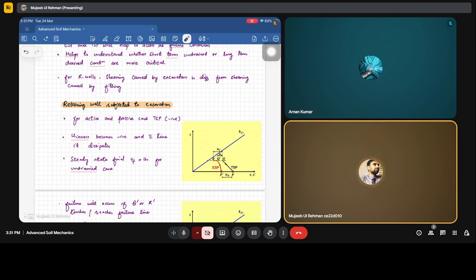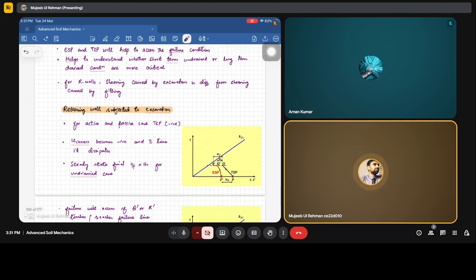We reach point Q. Now when we are doing the excavation, we are taking the soil out. You have to remember that in case of sampling, when we are reducing the effective confinement, there is a kind of suction which is holding the sample. So similar to that, you can take that as a benchmark or an analogy here: due to this excavation there will be the generation of negative pore water pressure, and this negative pressure will try to make things stable during the excavation.